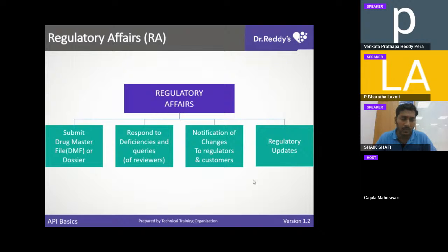We put a 1 kilo weight on the weighing balance and see what result it shows, 1 kg or something different, because here the standard is the 1 kg weight which we kept on the balance. We check against the standard. So based on the type of instrument, the standard will change.